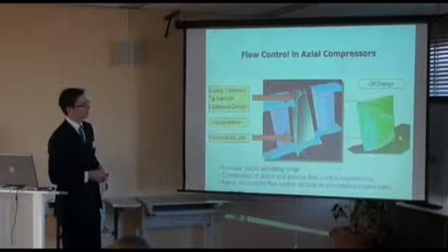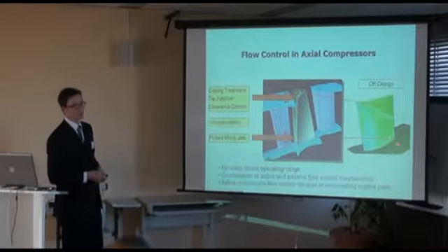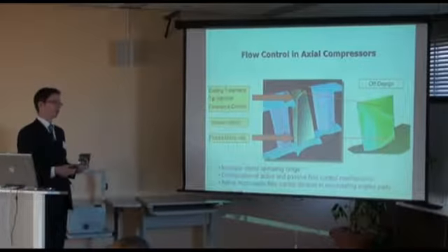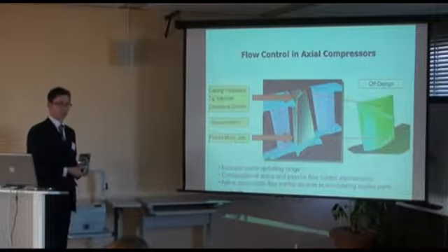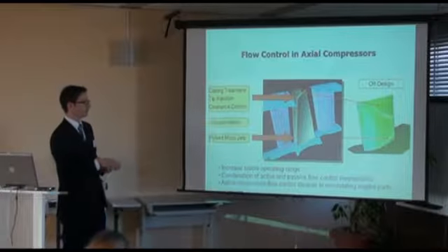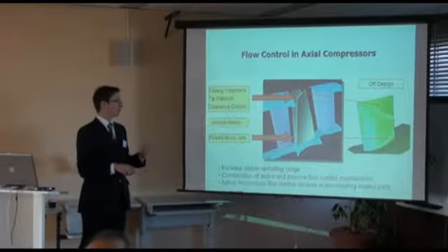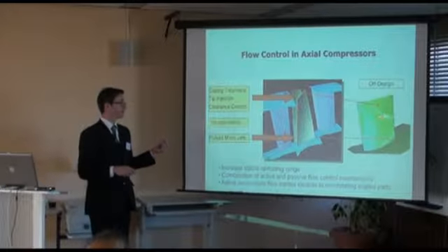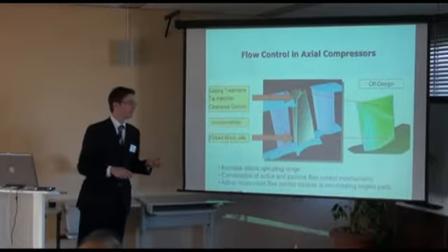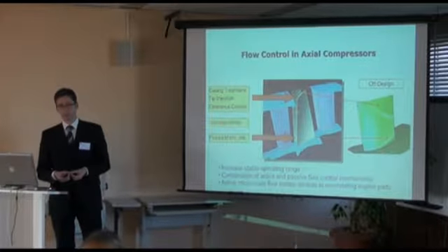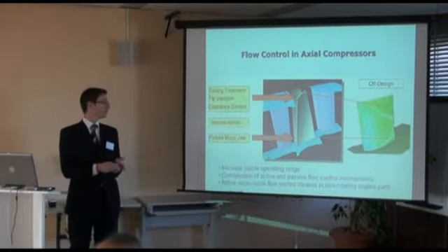And there also, you can have separations on the trailing edge, where you can apply microjets and manipulate the separations in this region. You also can have variable airfoils to provide changing shapes of the airfoil geometry to improve the flow on the airfoil itself.